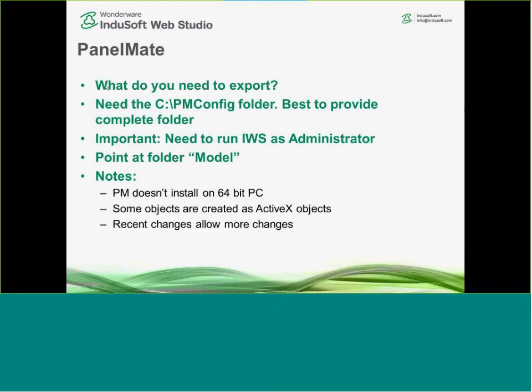What do you need to export? First of all, that's the important thing. What do you need to export? And it's kind of a step-by-step to do this. The first thing that you need is when you're using the PanelMate tool, it's going to store everything typically in a PM config folder. And it's best to zip up that entire folder and provide that. We've had applications where people have tried to just surgically remove the individual things that they need, and it turns out that we really do need everything in that folder to be able to bring that in.